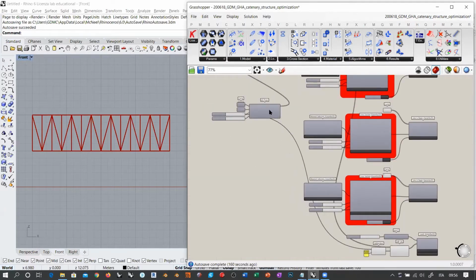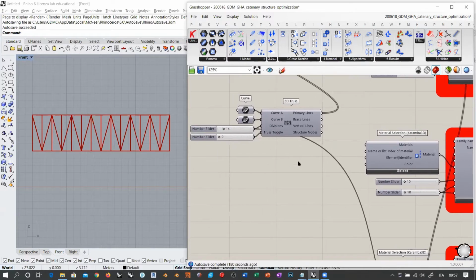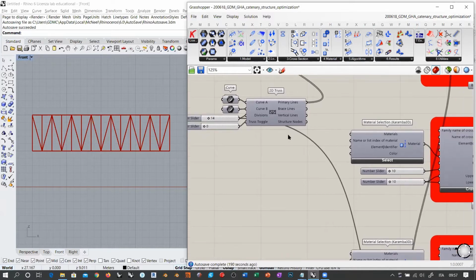Well, here we could do several things. We can anchor this structure, for example, only at the bottom if we want to create some kind of truss beam. Or we can anchor all the four vertices, the four corners of this structure, or only the upper corner. You can do whatever you want, basically. And you can also use different types of supports, of course, like a fixed support here, and here you just place a translation support. But anyway, let's keep it simple once again.